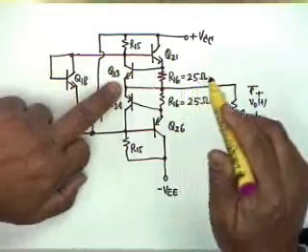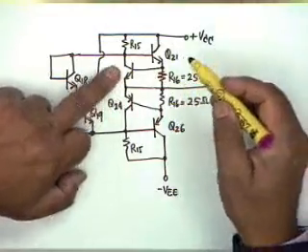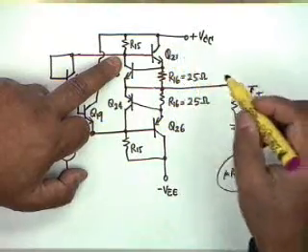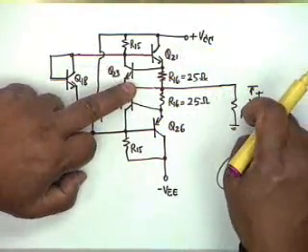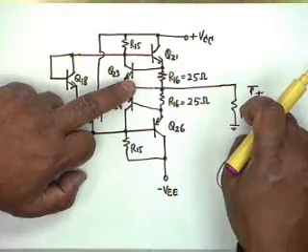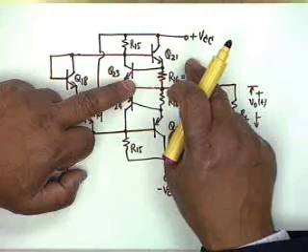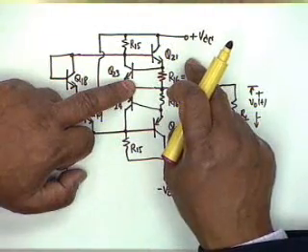During the positive half cycle, Q21 is supposed to conduct, and if R16 is 0 and RL becomes accidentally short circuited, the transistor Q21 will have to put up with the full drop of VCC from its collector to emitter. It may be too much for the transistor.